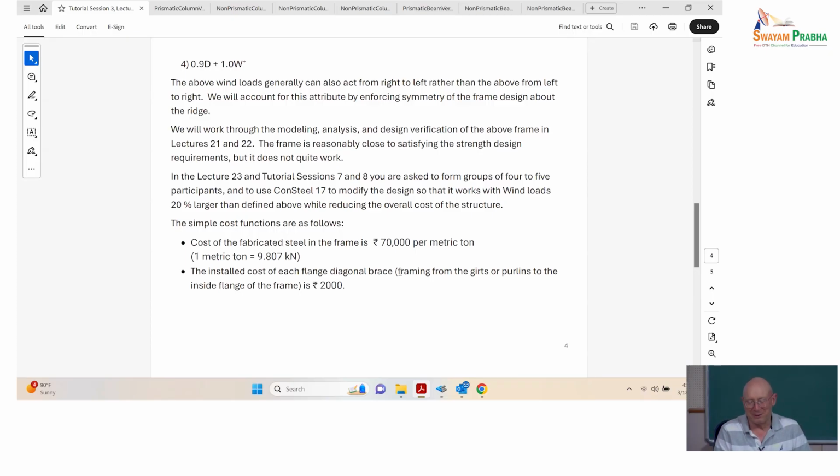So one thing to think about, I guess I'm kind of tipping my hand here. One aspect in terms of the cost, and you remember I mentioned that with these frames, metal building manufacturers will typically, or many of them, will do a design of the frame first, where every purlin and every girt location is assumed to be a brace point, unless you know there's going to be a door or whatever where you can't get bracing somewhere.